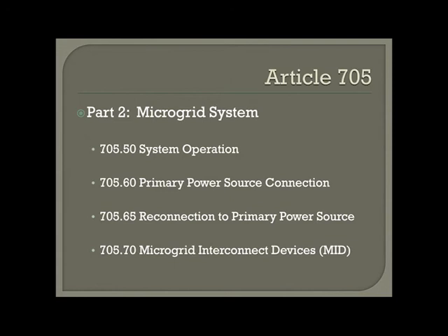So when you do put your stickers on for your voltage and your amperage or your KW, whatever like that, make sure you fill it out. Don't just put the sticker on there, fill it out, because I can't do a load calculation. So if I can't do a simple calculation, because I don't like math, unlike these guys, they like math, I'm not going to let you put more than a 50 amp breaker inside the house on that panel if that's where you're coming off of for power.